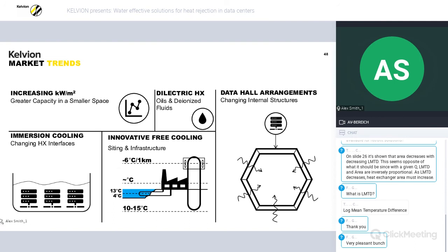As I'm sure most of you are aware, there is an increasing demand on the white space. We're seeing growing compute capacities within smaller footprints, exponentially increasing the thermal demand from heat rejection systems. Considering an industry which has hardly changed fundamentally for 100 years, we have to find efficiency gains through fine-tuned refinements and innovative application of design. The growing adoption of immersion and liquid-based cooling solutions in the white space are leading to changes in process fluids, such as corrosive deionized water and viscous dielectric oils, and elevated temperature profiles.